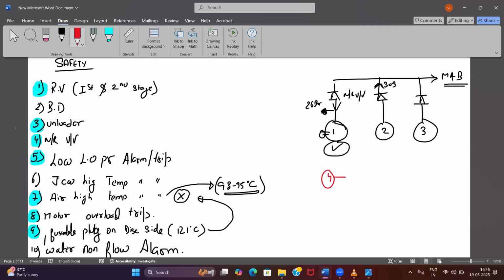Because in four stroke, in every four cycle, in every two revolutions, I have one power stroke. So for the other three strokes, who is supplying power? The flywheel, sir. So I will require a bigger flywheel which can give for these three strokes. Agree? Yes, sir.